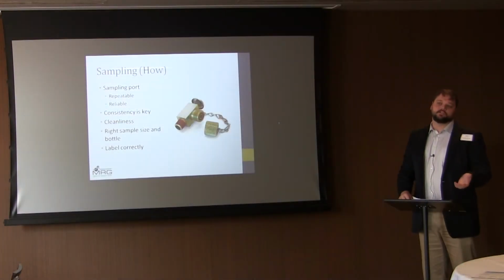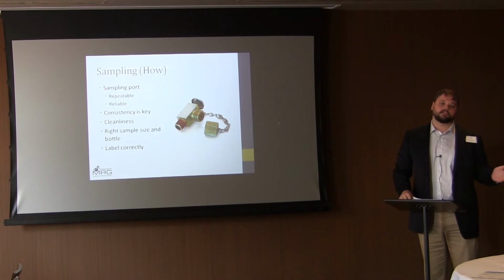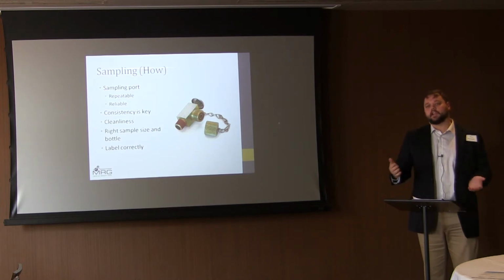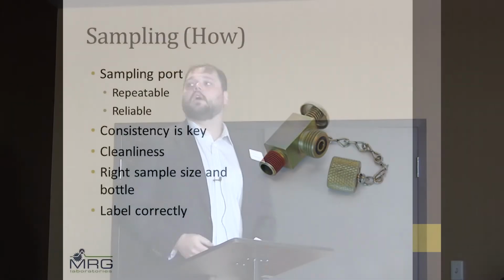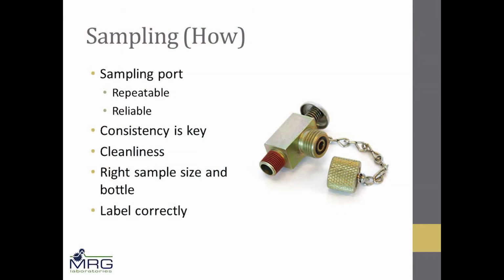It makes it easier. That consistency allows you, when you do take a sample, to then trend your sample over time. So ideally when you're taking samples quarterly or biannually or even annually, depending on the equipment, you have that trend. So you can see, 6 months ago or 4 months ago, our oil looked pretty much the same, we've only lost a little bit. You can kind of just know what's happening, take action, and that's going to cue maintenance or anything like that that might need to happen.